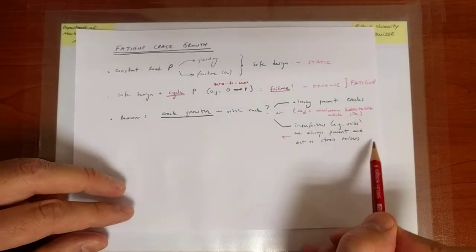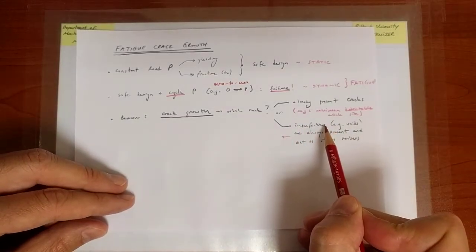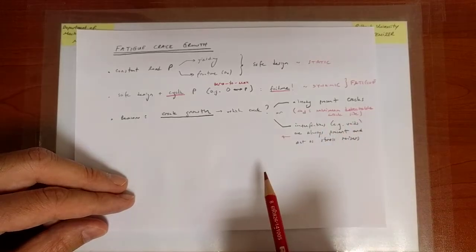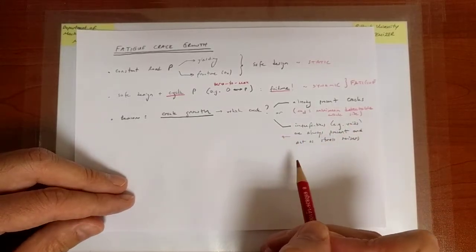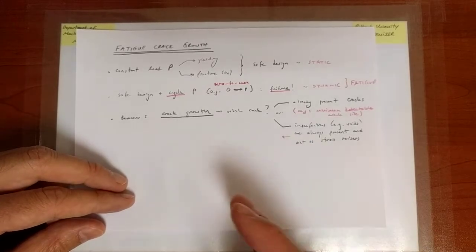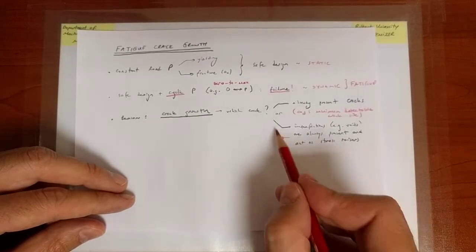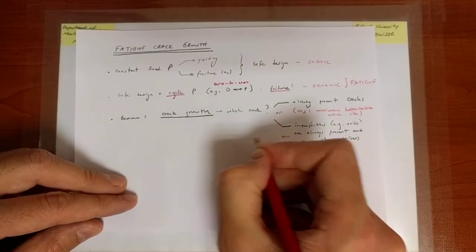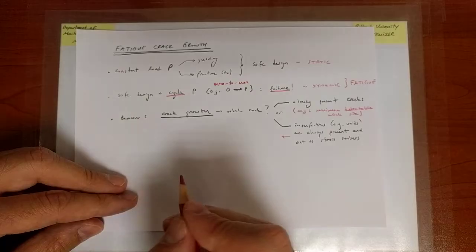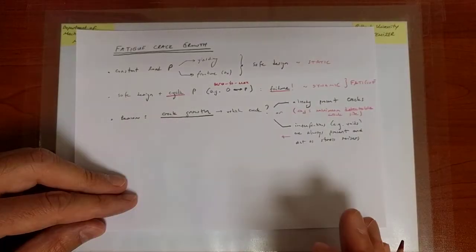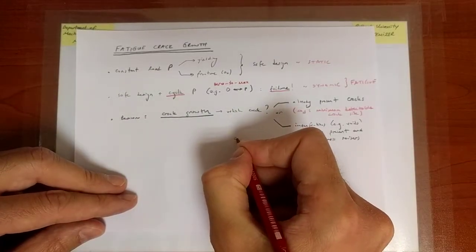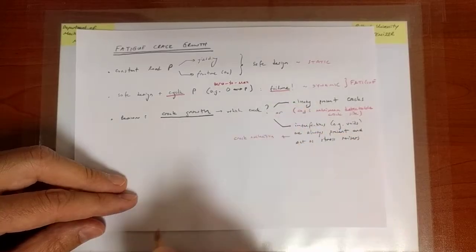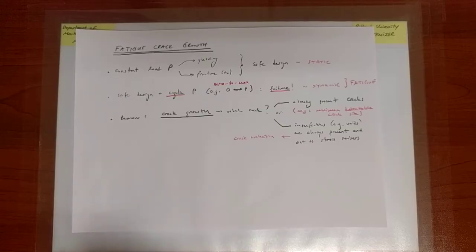So for instance, if this were a brittle material and the stress concentration due to the void exceeds the ultimate strength of the material, locally there could be a crack that forms during loading. And as soon as that crack forms, you're back to the first scenario. You have a crack and it will grow over time. So even though you think you may not have any crack, and in fact there isn't any crack, a crack might nucleate. So one way or the other, you end up with a crack.